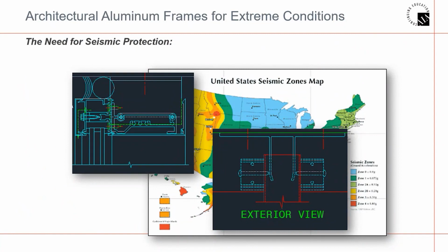Based upon the amount of movement anticipated, joint sizes might have to increase to absorb more movement. You can see in the illustration on the left that we've increased the size of the joint at the head of the curtain wall to accommodate more movement. The anchor detail in the center shows how the top of the vertical stops shy of the anchor, increasing the amount of space there, allowing for greater amounts of vertical deflection to occur.